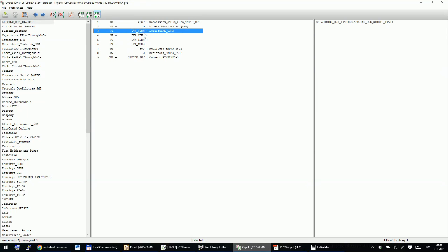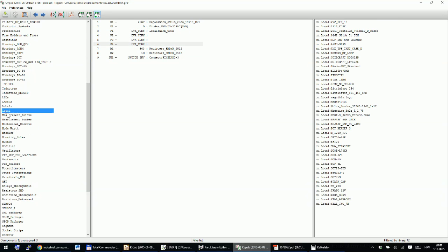So I need to find, you can see I have 3 unpopulated footprints for my project, and I know already that they are placed in the local library and they are named WireCon. So I will click on first one, and then I will double click. This is a bit tricky. First time I couldn't find how to choose it. And I will double click on WireCon, and I will do it just 3 times, because every time you click, Kicad just moves on to the next unpopulated component. Okay, and I will save it.